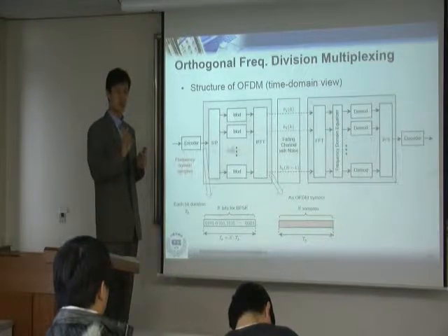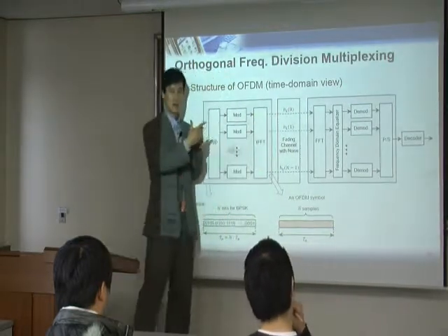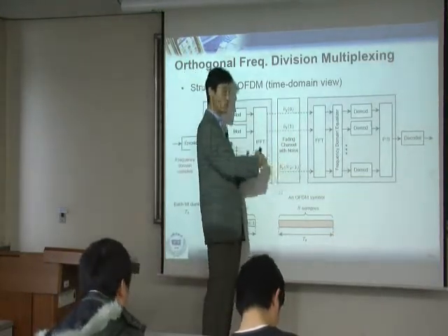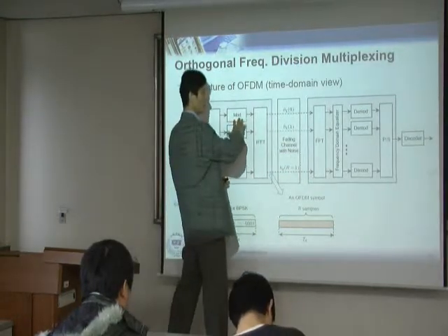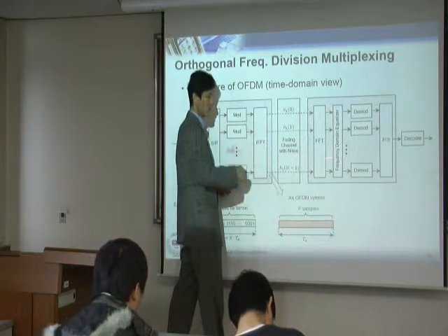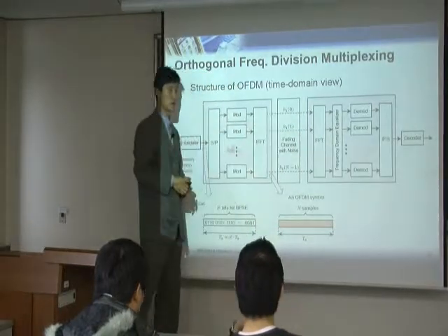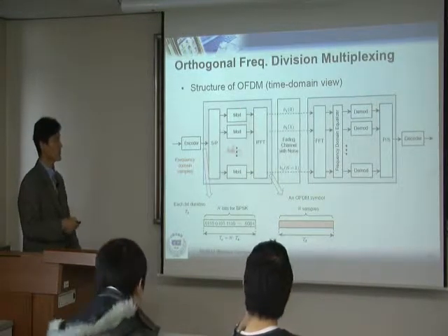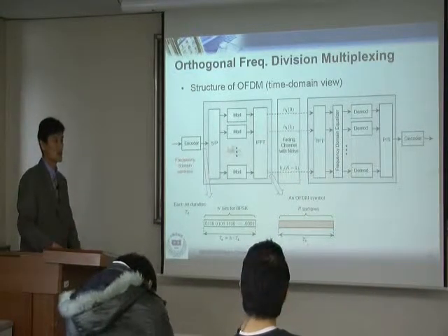That's based on the relationship, right? The ratio between the symbol duration and the multipath delay. There's always a relationship. If the symbol duration is much larger than the delay, then it's frequency flat. So once you divide this into multiple parallel paths, each parallel path becomes frequency flat, and each one is independent. That's what is happening in OFDM. That's why people say that in OFDM, you are basically changing the frequency selective channel to frequency flat. That's why they call it that way.